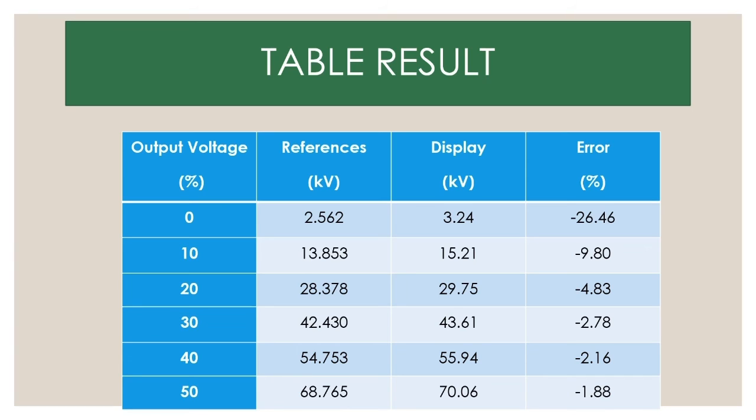It's the same as Lab 3 for AC high voltage, which is 10 microsecond sampling intervals. And for the coupling for this lab experiment, we set to DC because this experiment requires us to determine the DC voltage generation.